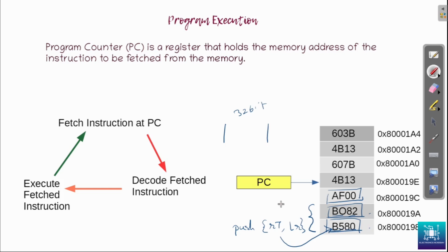So this keeps happening. In our case, the address actually starts from 8000000. Why the code did not start from there is another topic of discussion, because we will have something called the exception vector table in the beginning of the flash, and they say this is from where the actual code starts.